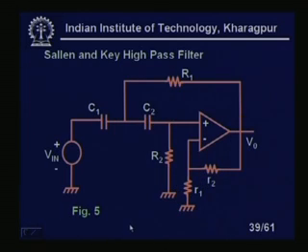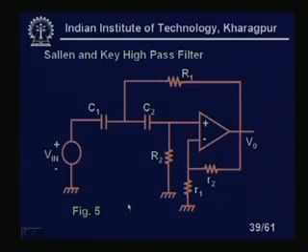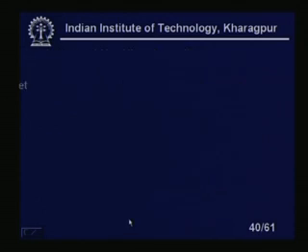So, it is fixed. Now, this is a high pass filter, you can see we have interchanged resistances and capacitances, right. So, if you interchange the resistance and capacitance, I will get a high pass filter. And you see this is a very handy circuit. If I know the design equations, I can make my own filter. It does not cost much, maybe 5-6 rupees. Only the op-amp is costly, the resistances and capacitances can be ordinary, right. But we need a certain amount of tuning. Whatever prescribed center frequency, pole frequency we have asked for, we may not achieve that particular frequency. We need a little tuning, because the sensitivity of this type of structure is quite high.